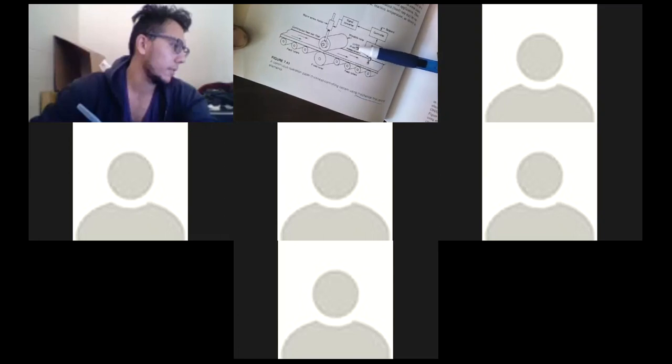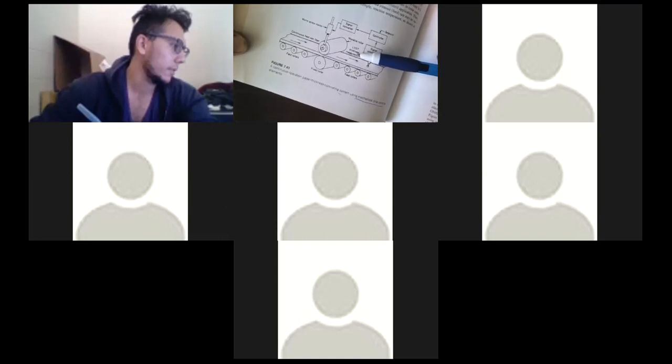The sensor is a position sensor called the LVDT. Remember the sensor we talked about? LVDT sensor. So the LVDT sensor will be sensing the thickness of paper, and this PID control will control the electric motor, and then push the roller. So the thickness will be consistent